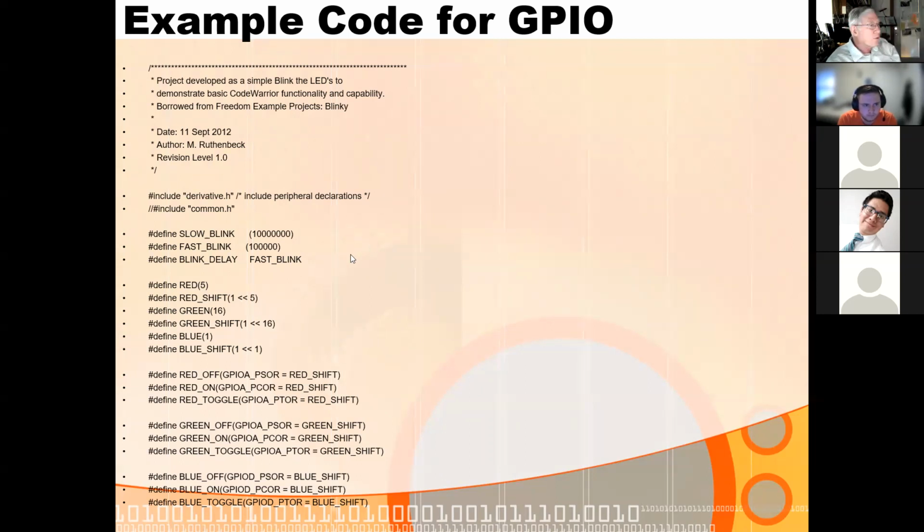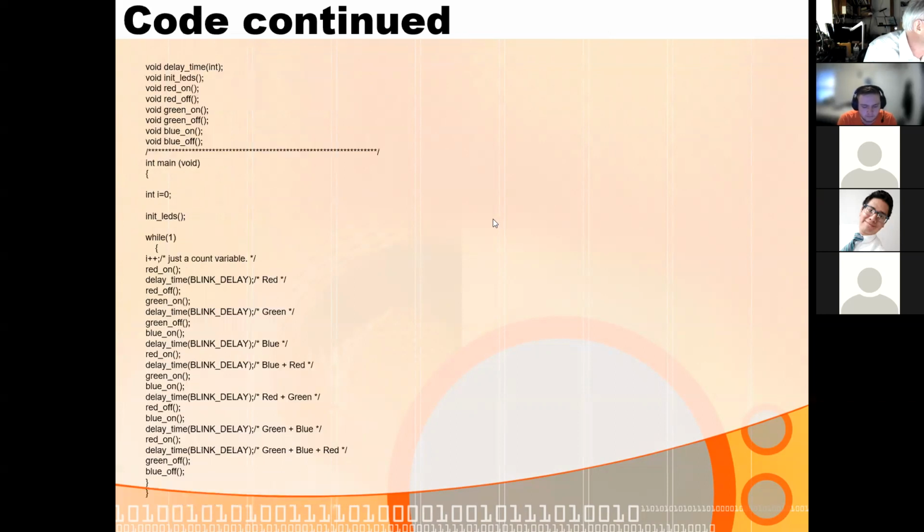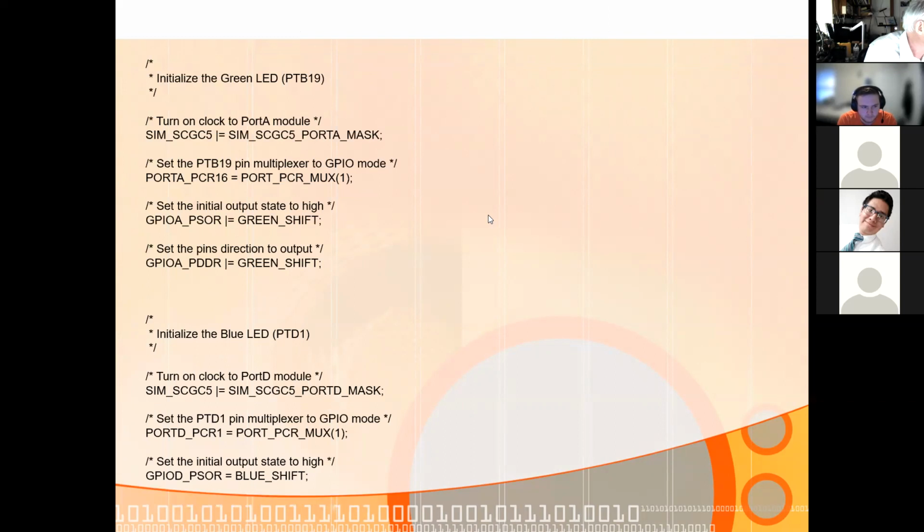We're kind of coming up on time, so let me just go through what it takes to get these things started. Here's what it takes to just get ready to use a GPIO pin. The first thing you have to do is turn the clock on. Now in Code Warrior, we just issued this instruction. But in MCU Expresso, you're going to use a data structure and a function call, a method within a class, to do this.